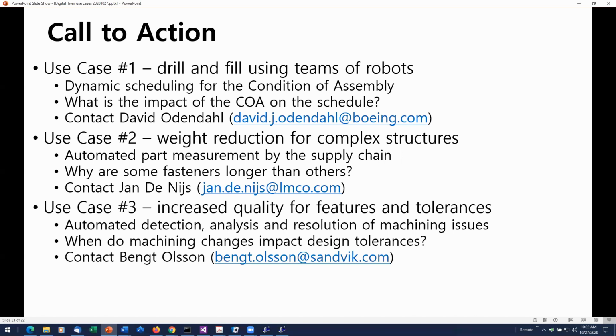When we look at that machining data, we look at what's being worked on, what feature am I trying to machine, what tolerance does that feature have to meet, so that if there is a machining change, an override in this case, but it could be something else, it could be an abnormal load detected during the machining, or being a bit too close to the end of the tool wear, we know we need to do some additional checks.